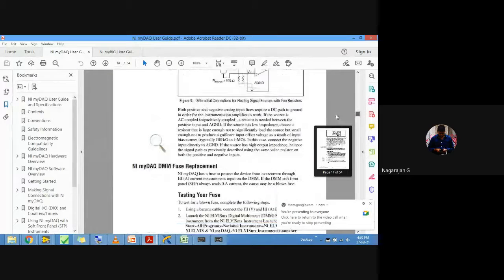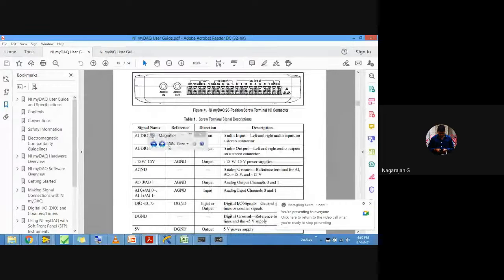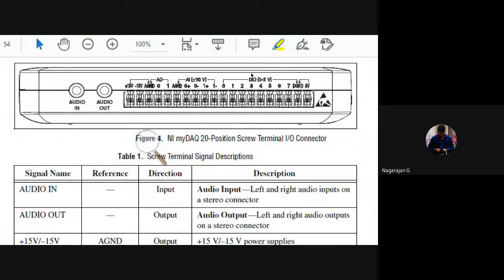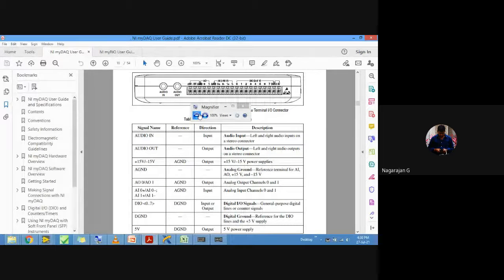Okay, so I'm looking for the IOs. If you look in this PDF, the thermocouple comes under the analog family. A thermocouple has 2 wires, a 2-terminal device, so that will be connected to AI0 plus and AI0 minus. Once your thermocouple is connected, I need to develop a logic. The output will be in terms of voltage, correct?